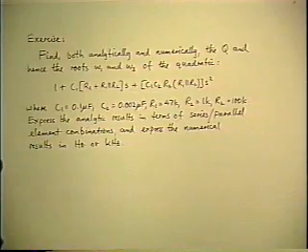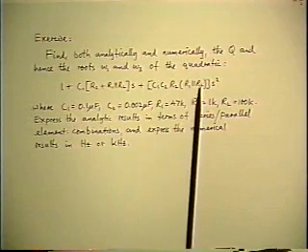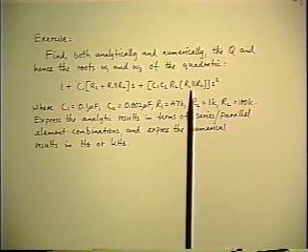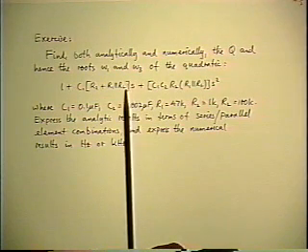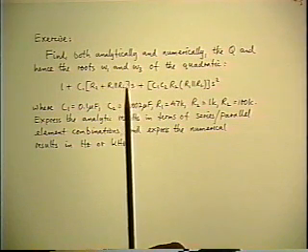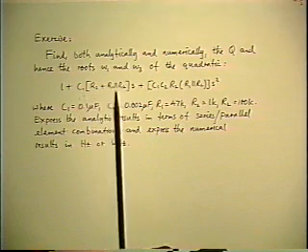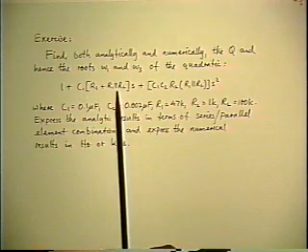Now we go back to where it came from, which was that low-pass filter network with two capacitors that gave rise to a quadratic equation. And here it is again. This is the denominator of that voltage transfer function for the network that we already looked at, after dropping out the second part of the middle coefficient, using the numerical values to justify analytic approximations.